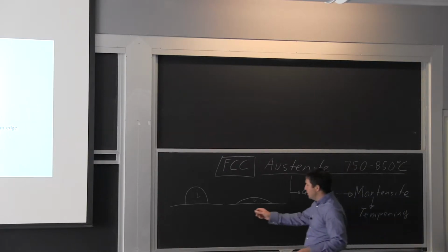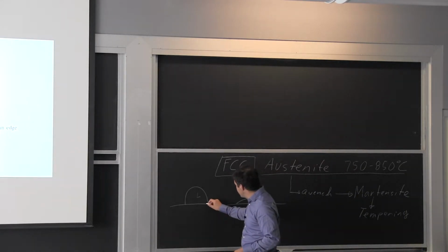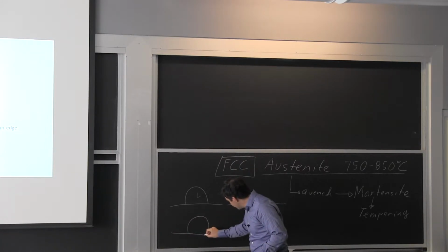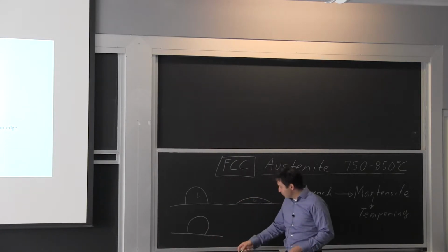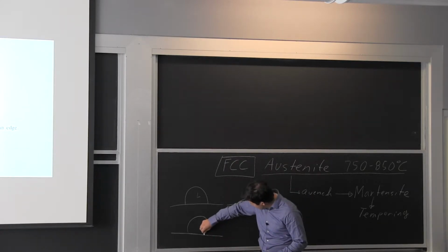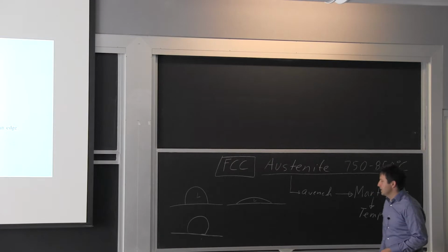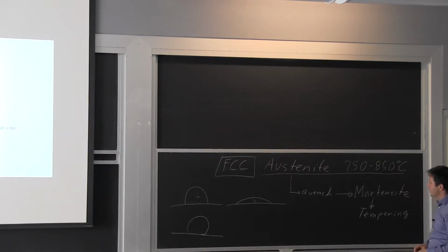In welding, you can have the situation where it's actually coming back on itself. It's the extreme scenario. So you get the bead that is a little bit like this, and that almost guarantees you that you didn't have enough temperature to fuse the base material here. That's how we use it in practice.